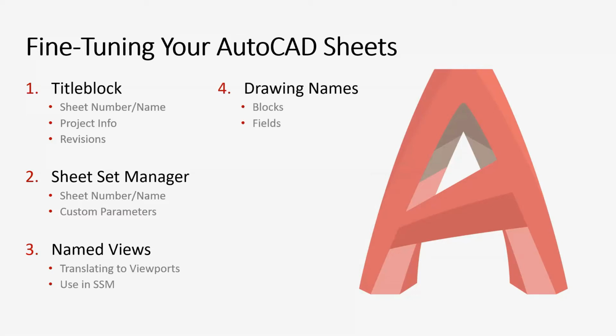In terms of some drawing names, we'll just basically create it into a block so that we can reuse it. And we'll just play around with the different fields that we can have in there to make it a really smart little block. And we'll have a look at some annotative text just to make it a bit faster in our paper space. So that's basically just to deal with scaling issues in our text. And then one extra one will be the project navigator.